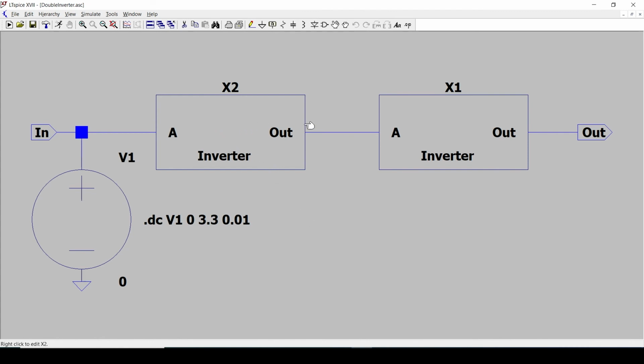For completeness, there's one other circuit we look at completely. Here we have just got two inverters, and remember, when an RS latch is in the latched state, then the output of this inverter gets fed back to the input of the first inverter, and that's what gives us memory. It just keeps remembering what its output is, and it stays like that.